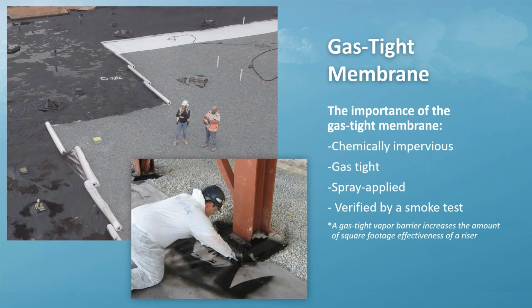We're going to show you not only the health protections, but the cost savings at the end of doing this right. You want to have a spray applied vapor barrier that gets those seams gas tight. And I don't care what anybody says, you cannot get tape to stick to column pads, sidewalls, as well as you can a spray applied barrier, because this spray applied material, when you spray it down, it's tacky, it's like an adhesive. And what it does is it fills up all the pores and bubbles in the concrete, and you can get a nice gas tight seal to that particular column right there.